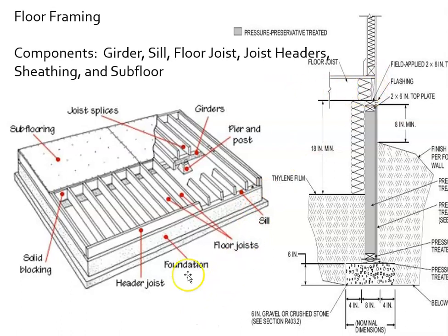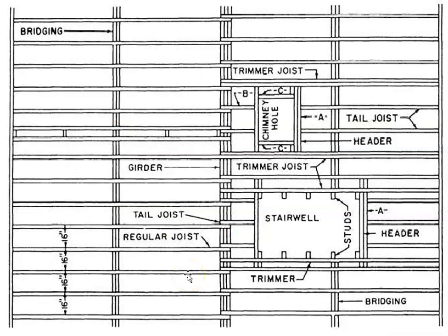Okay, and then the joists run that way. All right, so again, this is not a construction document, but it's more of an illustration of the different parts. So we can't see the foundation wall, which would be here. The load-bearing wall would be here and here, and here's a girder coming right down the middle, and I would call this a triple built-up girder. So it's made up of 3 different boards, and they are nailed or bolted together. And then we see the joists extending from foundation wall to girder.